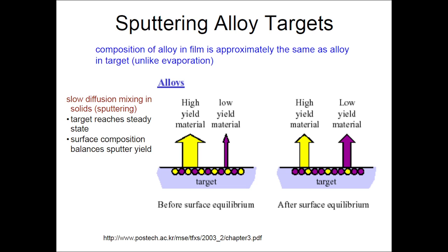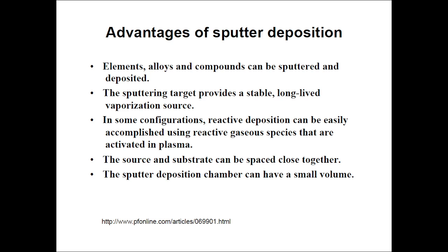So that is why we do a pre-sputtering process in sputtering. Pre-sputtering means before you start deposition we sputter the atoms with the shutter closed. It is just initially to ensure the proper composition. Once we ensure the proper composition we can start the sputtering further.